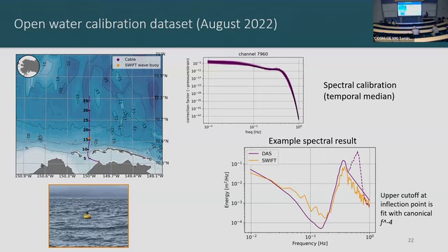Then from applying this calibration back to the strain spectra, we can get from the DAS a calibrated wave spectra. The initial spectra that comes out of that is the dash line. There's some additional QA and QC that we need to do to make a reasonable, physical looking spectra that we can get bulk wave parameters from.